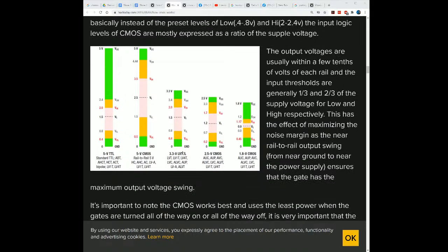And we see that low voltage TTL, there are some of the 3-volt parts. And as you get faster, you typically get less voltage. And one reason is you simply don't have to slew the voltage as far. You don't have to throw away all that energy.